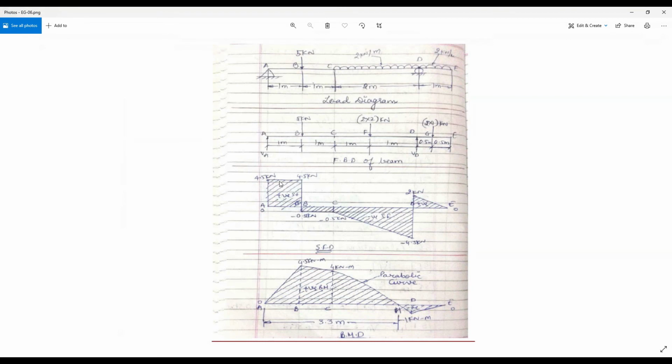Now the direction is reversed because of the assumption of which direction you are taking. For example, if you take upward forces to the left of section, if you recollect the procedure for solving, the sign convention for solving of SF for particular points on the beam, then you would recollect that we have used upward direction as positive. In ANSYS, upward direction is negative. So that's why it's just reverse of what we have got as a solution.